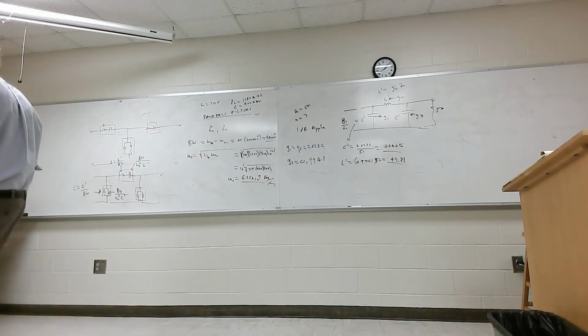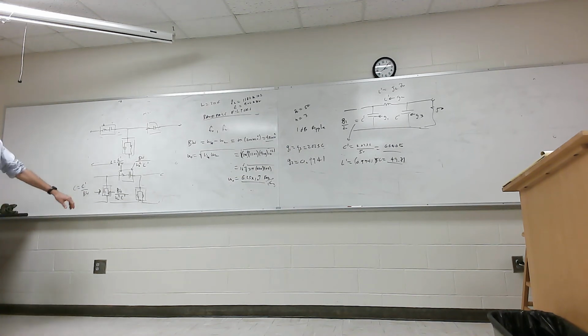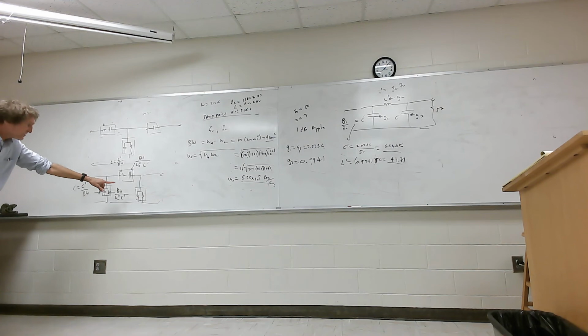I will say one thing about this. I probably am not going to give you a band pass or a band stop. For band stop, you just replace this so that the series elements become parallel, and the parallel elements are in series. I would probably give you high pass or low pass. I'm just leveling with you. I don't want to cause you too much of a problem, but you should be fine to do the homework and understand it, okay? See you on Friday.